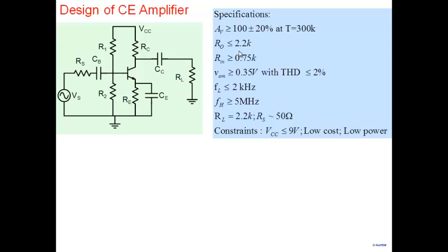Well, they may be coming from the specs of an ADC. Your whole 4-stage amplifier may be a part of an analog to digital converter. So from the analog to digital converter, you look at the block diagram and the specs of the A to D, and from there you find out that you need certain specs for an amplifier. And from the specs of the amplifier, you derive what the specs of your stage here should be. So it's coming from there.